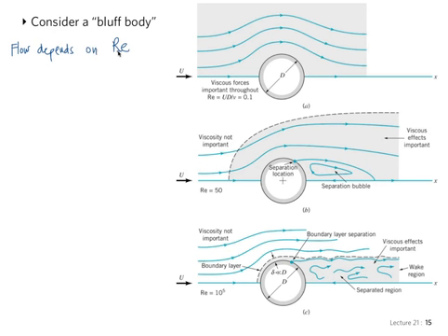It depends on Reynolds number, like for the case of a flat plate, but it has the additional feature, which is separation. So, first for low Reynolds, similar to the case with a flat plate, we'll have viscous effects important in a large area.